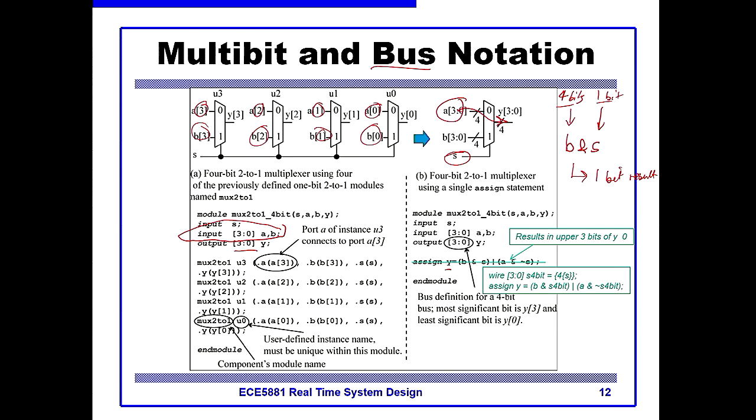So that 1-bit result is generated by matching up the bits that it can from the least significant bit upwards. So in our case, we have S as 1 bit, so it's going to match that 1 bit with the least significant bit of the B value. So the result of that would be the same as B0 ANDed with S. Okay, so that's what Verilog does. It allows you to mismatch things in an AND function quite silently and generate this 1-bit result when you actually expect a 4-bit result.